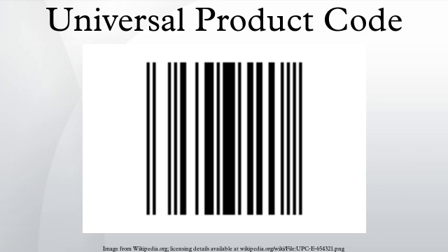Delta B compared bar widths to space width to code bits. This was extremely sensitive to ink spread, where too much ink or pressure would cause both edges of a bar to spread outward and too little to cause them to shrink. To make it worse, as bars spread, spaces shrink and vice versa.